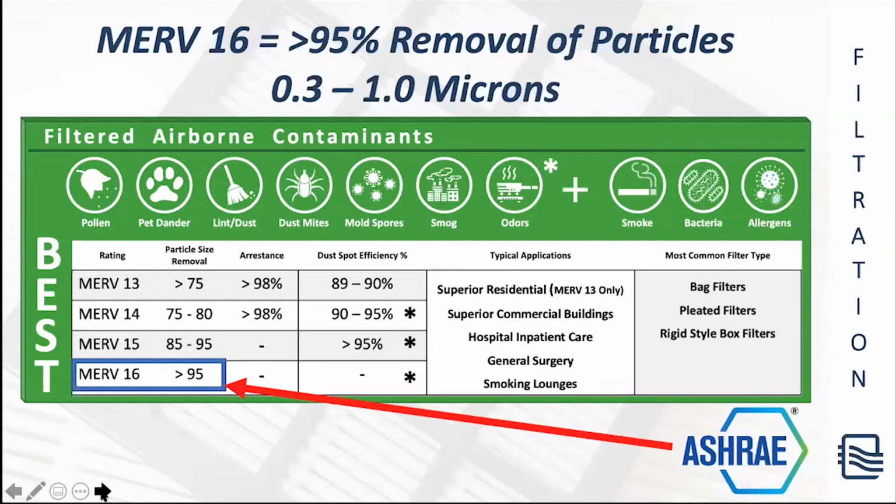Now, up until recently, the technology behind air filters was fairly stagnant. There hasn't been a huge increase in higher efficiency air filters until just the past couple of years. And so one of the purposes behind this webinar is we've got to understand that there are better options out there where we can still provide very, very high levels of air filtration, MERV 16 or above, and not negatively impact the air conditioning system at the same time in terms of that restriction.